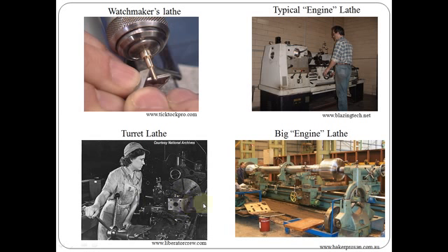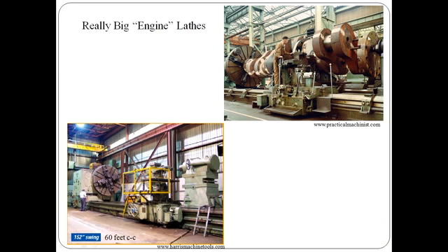The size of the lathe is decided based on the size of the workpiece. Here you can see that a larger work part has been held in a very large lathe. It is a very huge lathe used to machine a crankshaft for a very large engine. Here the carriage itself has a carrier to move the tools, and a worker may stand on it and operate it.